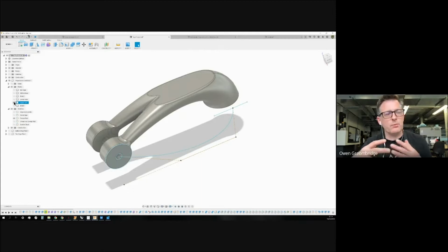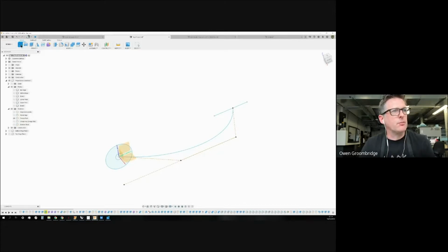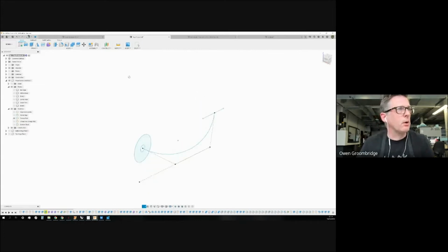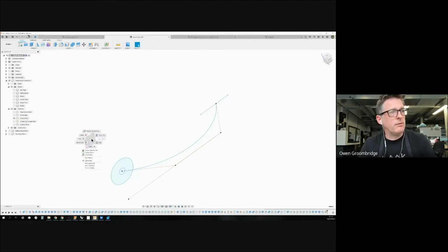It's done in sketch mode. So, for example, if I create another sketch, not that sketch, that's actually a bad example. There was a good reason why I had to project that. It's because I took the file of someone else and nothing was quite centered. Nothing was centered accurately anyway. So if I create a construction line, so I press construct there, select a plane, I'm just going to drag it off. As you see, I've right-clicked on that plane. I can create a sketch that way. Alternatively, I could just go to create sketch and select that.